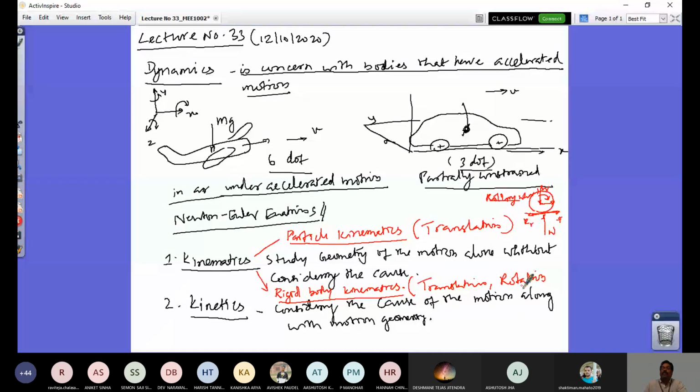So you can look at, suppose, a gear. A gear is only rotating. The shaft of the engine, the crankshaft, is only rotating. Whereas the piston in the engine cylinder is reciprocating. You see the connecting rod, which connects the piston and the crankshaft, is undergoing translation as well as rotation. So you see these elements are the smallest elements in a vehicle. But when I have to consider their design, the dynamics is very important.